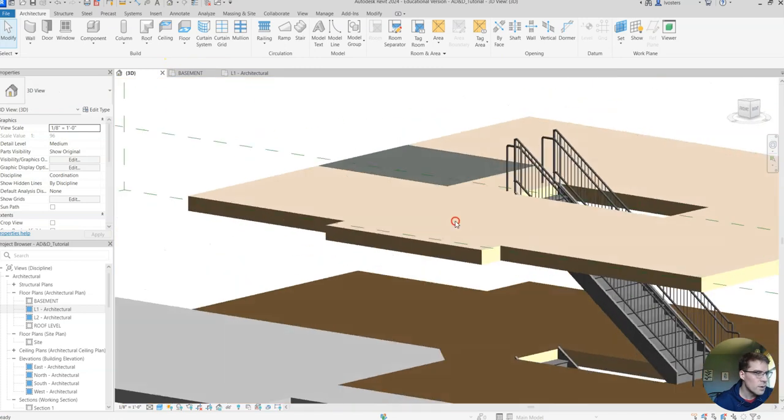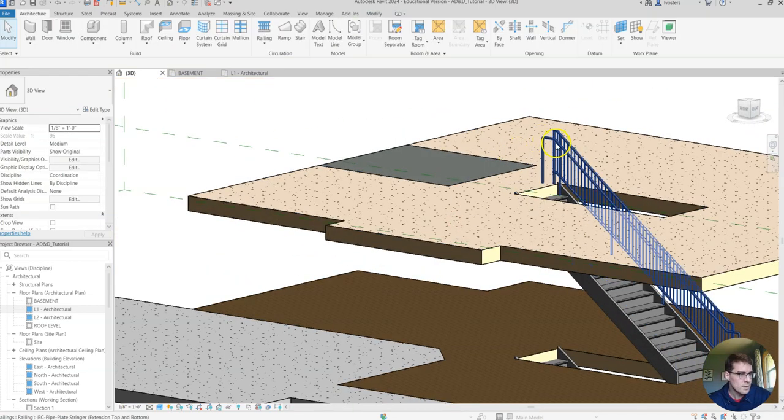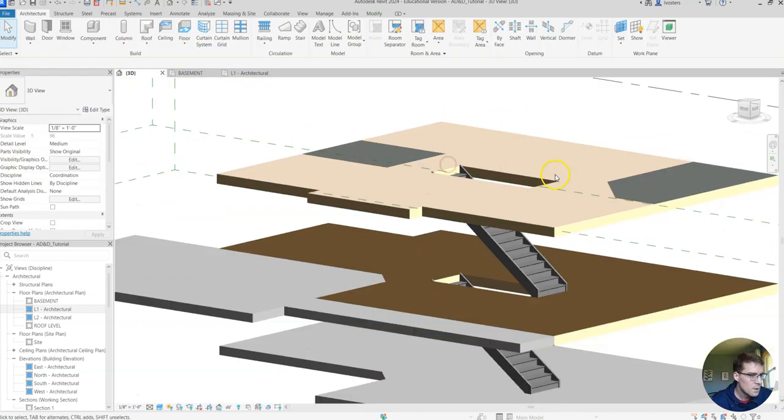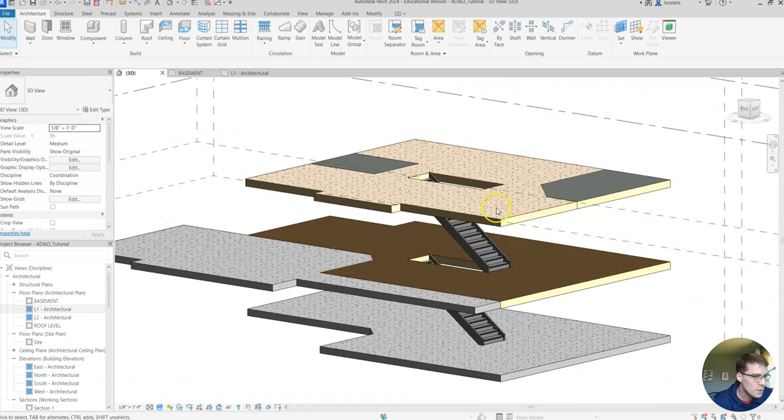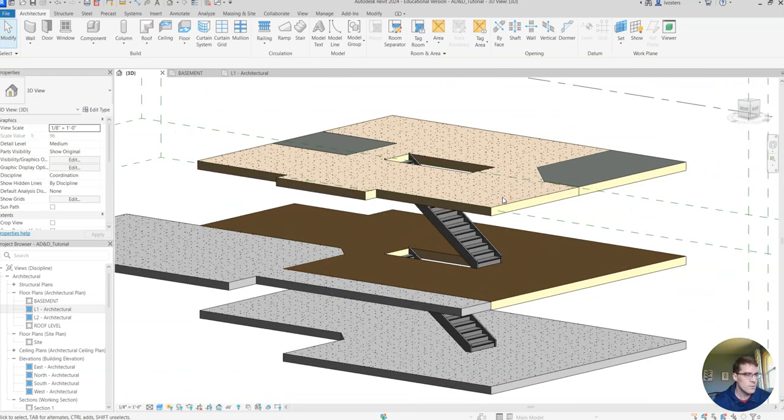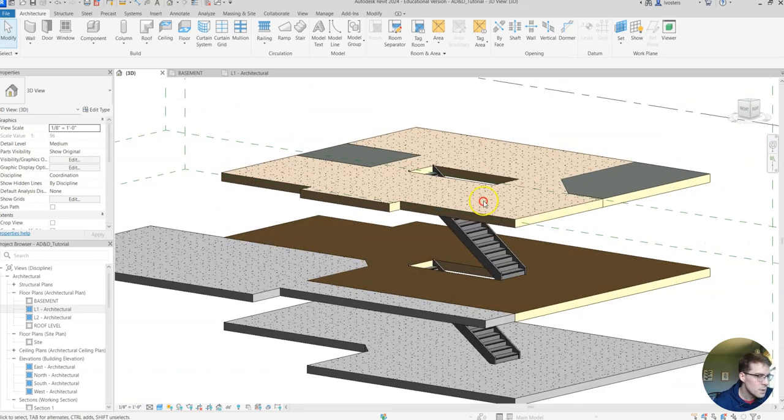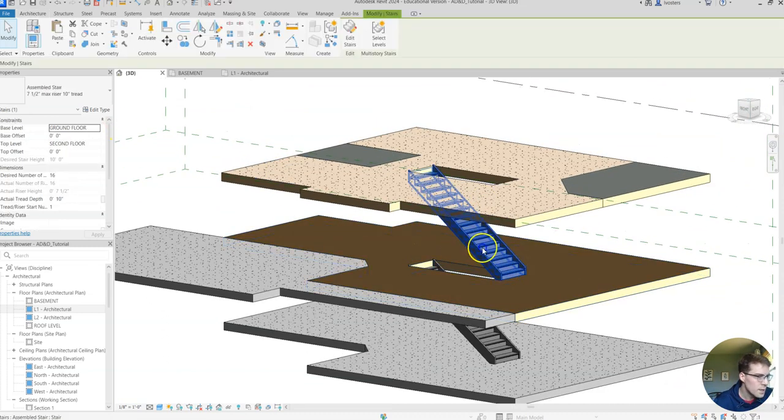All right, from our 3D view, we can click on our railings, delete those, but otherwise everything else looks pretty good. So I'm not going to drag this video on. It's a pretty short one, but stairs can be a little tricky. Make sure you do get it set up properly beforehand. Use that flip tool to get it aligned with this edge first. That's going to make your life a lot easier.